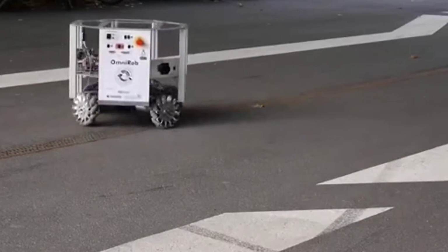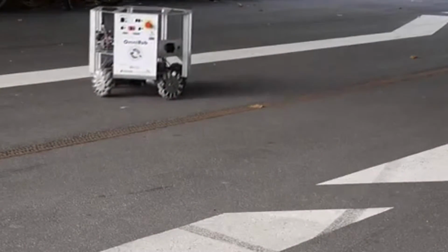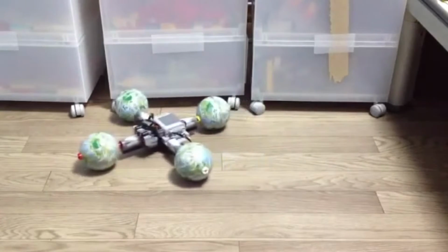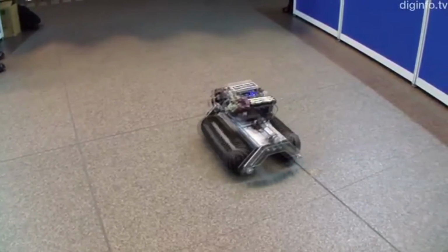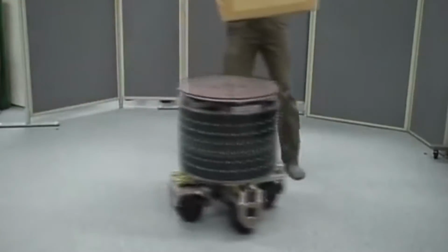One way to incorporate omnidirectional drive system in a robot is by using omnidirectional wheels, or mecanum wheels as the drive wheels. These are conventional wheels with a series of rollers attached to the circumference. By placing the wheels in correct orientation, the robot can move, or turn in any direction by varying the speed and direction of rotation of each wheel.